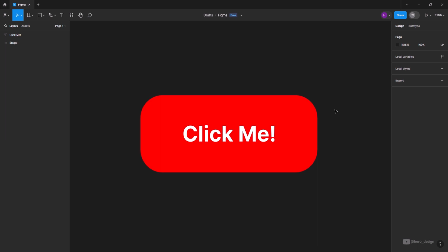In fact, components help us avoid repeating the design of elements and increase the speed of projects. In general, we have two types of components: master or parent component and child component. The parent component is the main one, and the child components are created by parents, and any edit done on the parent component will also be done on them.